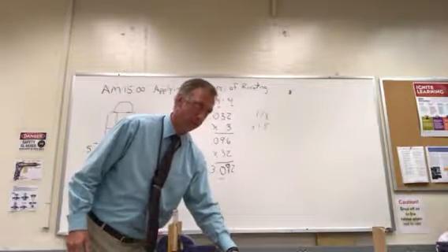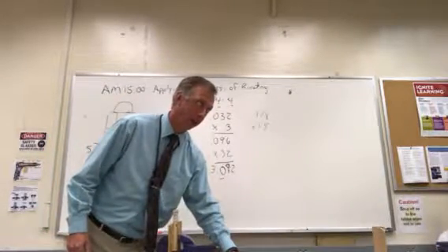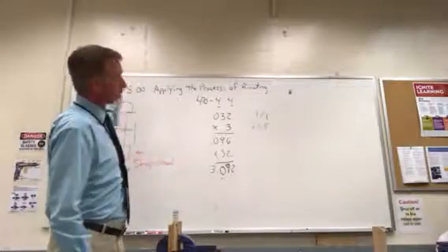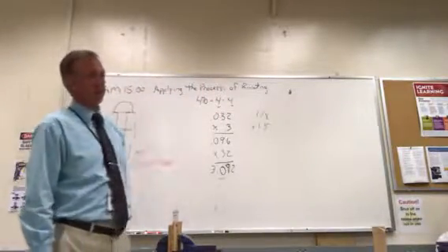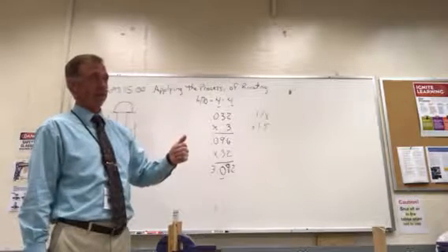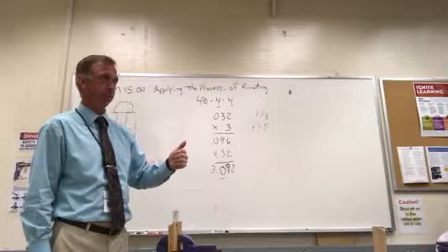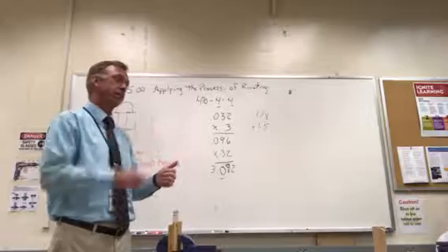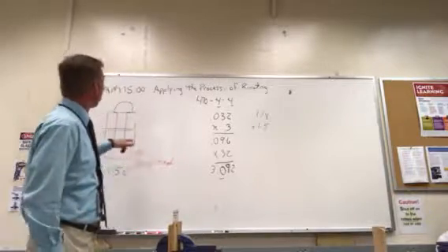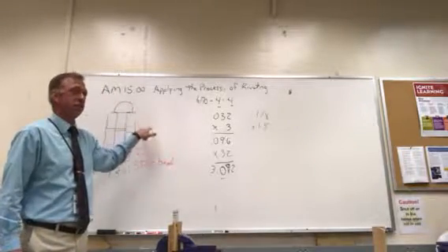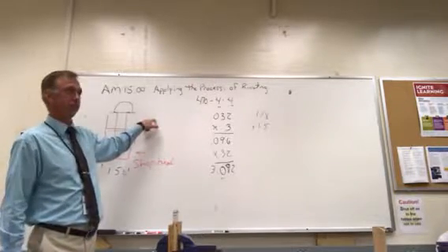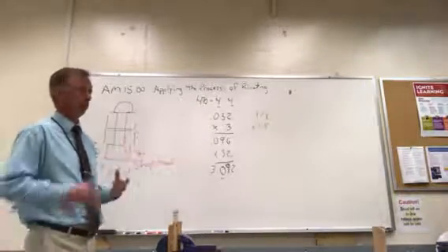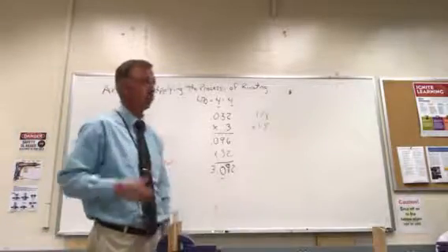Any questions about that? Okay, so what we went through is the process of applying a rivet, which means determine what size of rivet we need. And we determine the size of rivet by? Thickness times 3. Good, thickness times 3, okay? What if I had a 32 thousandths and a 20 thousandths? Take the 32 thousandths, good, so it's going to be the thickest. So thickness times 3, that's what we're going to work with.